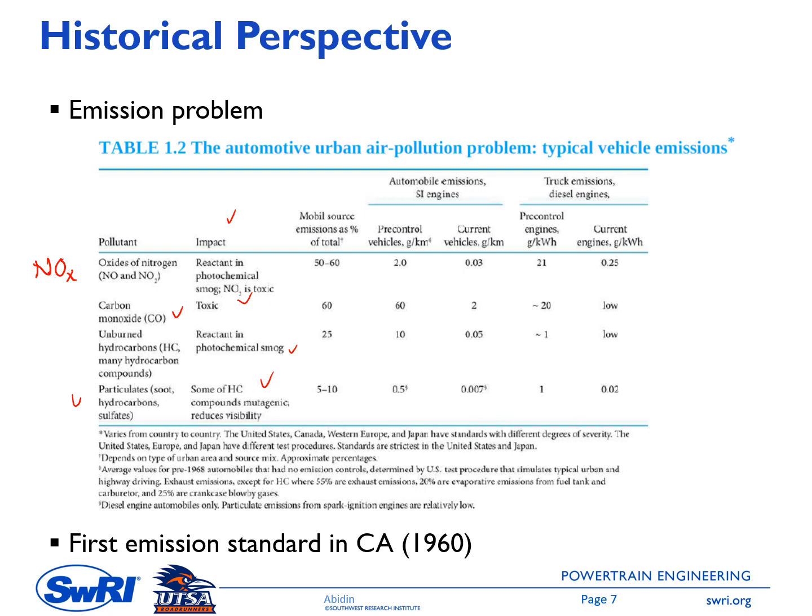The next column shows typical emission numbers from a different source, a mobile source, and then the next column is emission from automobiles. In this case, a spark ignited engine, which you can call a gasoline engine, although there are also spark ignited engines using natural gas fuel. This number shows the emission before the after treatment system is applied, so it's called pre-control here. And this is the typical emission number from current technology.